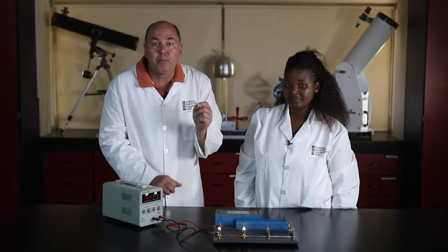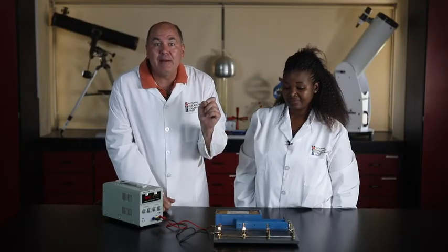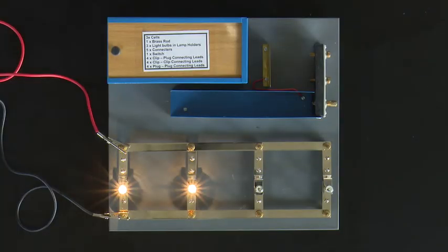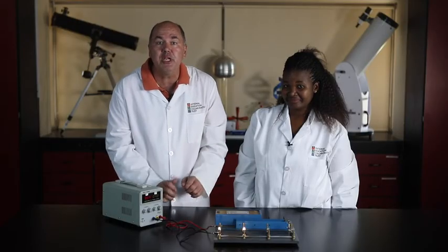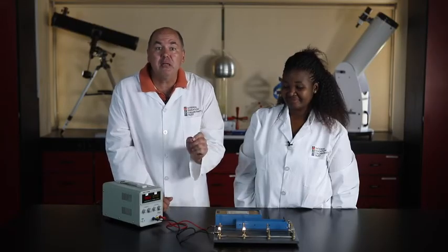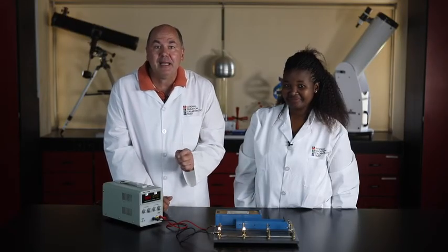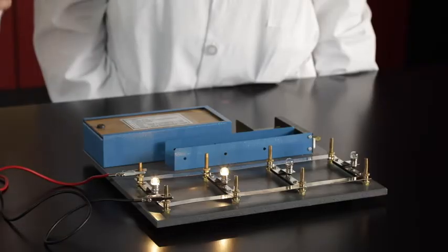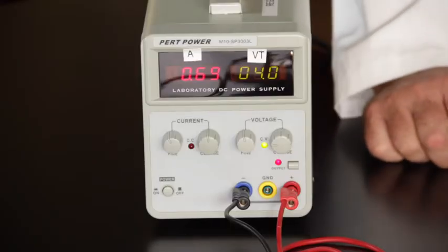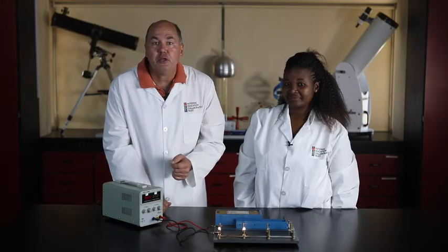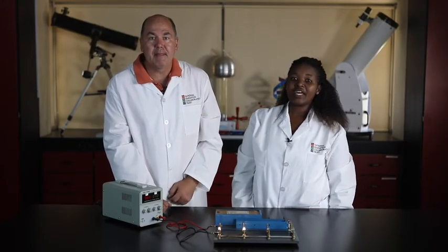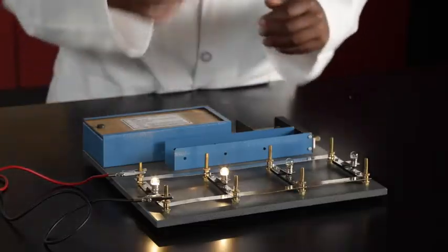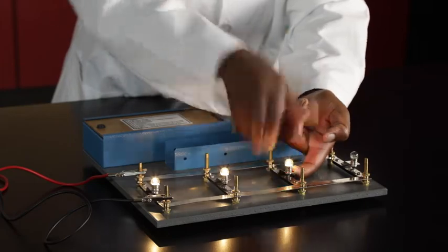The current through the power pack doubled, and because the second light bulb opened another path for the current to pass through, the main current from the power pack splits equally through each of the identical bulbs. Parallel circuits are current dividers. The current splits up as it passes through each branch of the parallel circuit, and it joins up again to pass through the power pack. So adding more and more identical light bulbs in parallel simply increases the current in the power pack. All the light bulbs shine equally bright.